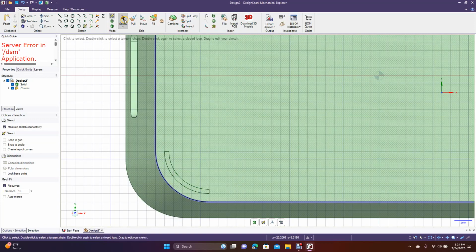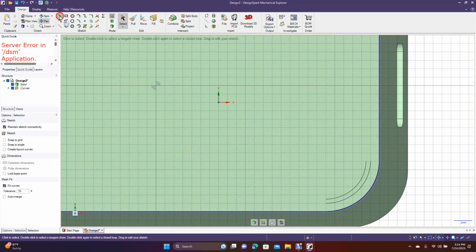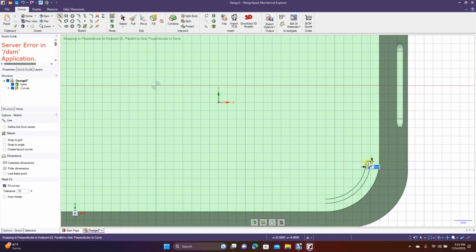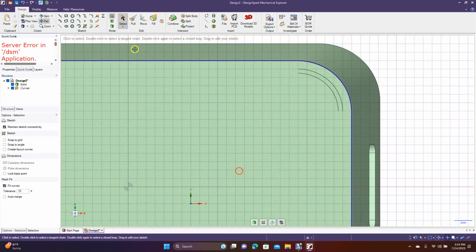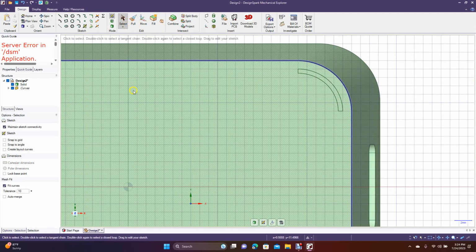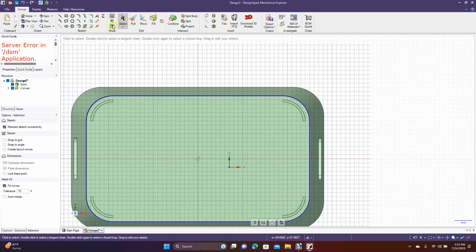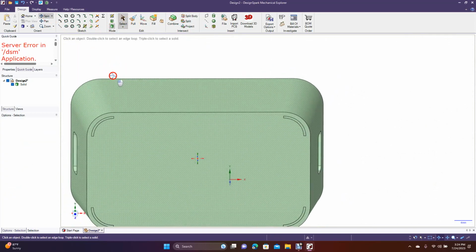Okay. Now let's go ahead and pan over. Get these last two here. Get the line tool. Endpoint to endpoint. Endpoint to endpoint. Select then click off. Let's pan down and do the last one here. Okay. So now we'll go ahead and Control minus. Let's go ahead and go to the 3D mode. Let's spin this. Make sure that's where we want to go.